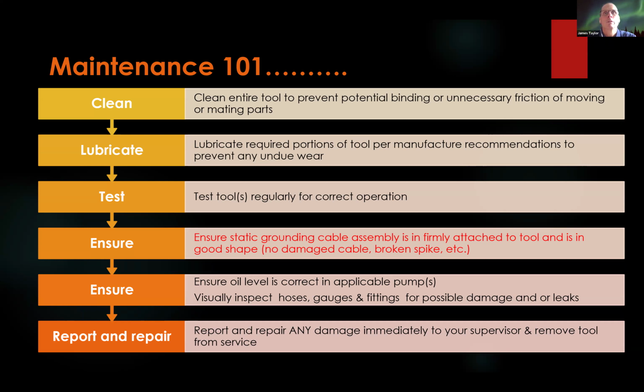Make sure our static grounds cable is in good shape and firmly attached, not like those pictures we just saw where it's broken and frayed. We want the most direct path, almost like taking a direct flight versus connecting flights. You want to get that direct path to ground.